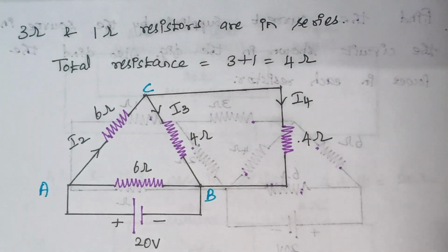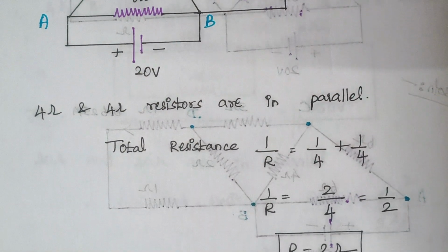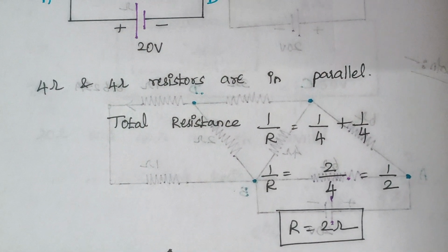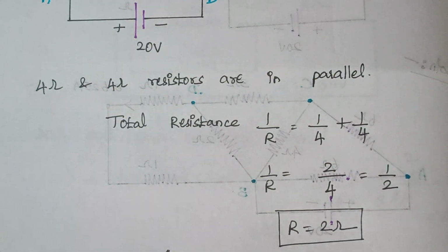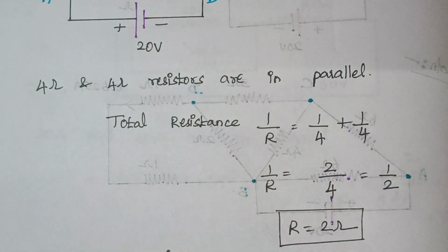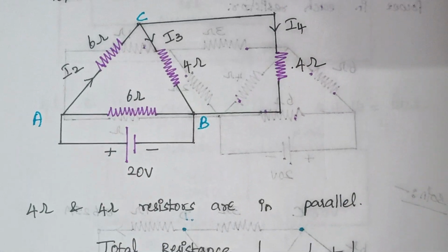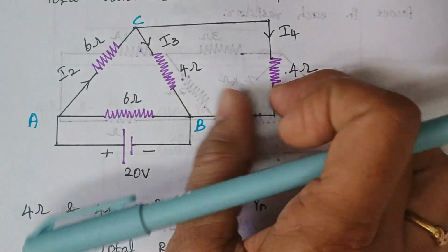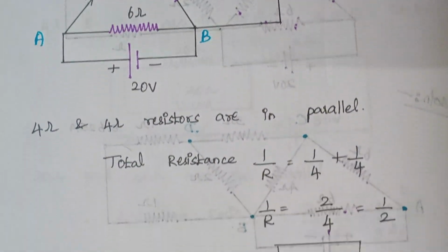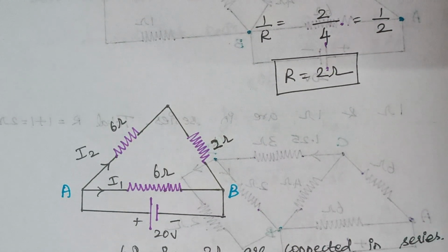So how to calculate the value when the resistors are connected in parallel? You see again the value is 2 ohms here. Here also you can directly use the formula R1 into R2 by R1 plus R2. Both give the same answer. So here there is a 2 ohm resistor. Therefore, between the points B and C, we had combined these two resistors, so they are now reduced to a value of 2 ohm resistors here.